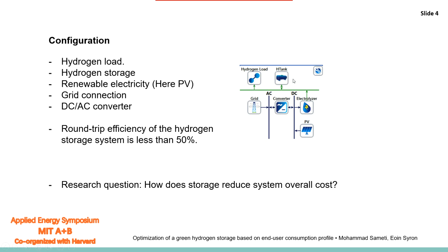And as we just mentioned, we need to store hydrogen in the compressed form. The primary electricity provider is the PV panels, which generate electricity in the form of direct current, or DC, and that DC current feeds the electrolyzer. As the backup, we need the grid, and since the grid is in alternating current form, we need to include the converter as well.